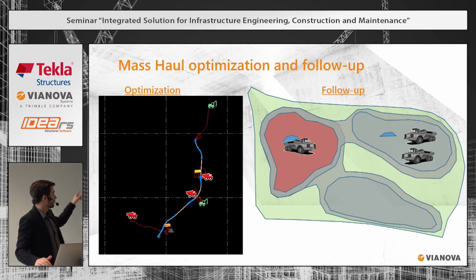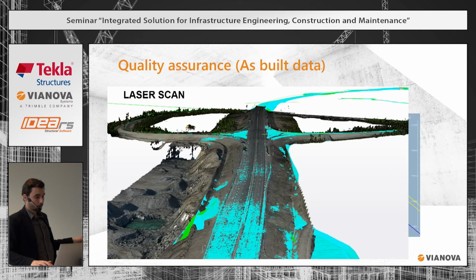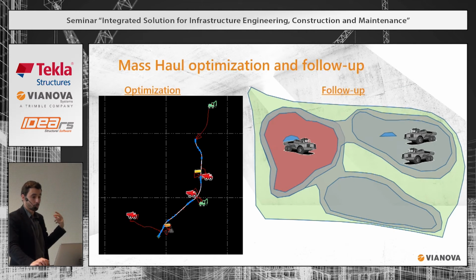You give certain points, you give the point where you can dump excessive mass, and the place where you can take the mass if you don't have enough. You can put there some boundaries like rivers and stuff. The program calculates exactly where you have to move dirt, from where to where. You put in what kind of machines you have, and how big a distance they can cover or deliver.